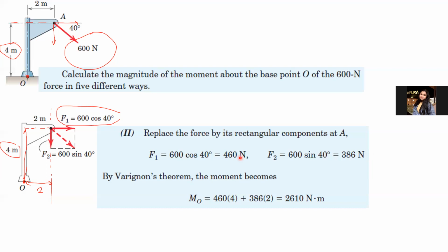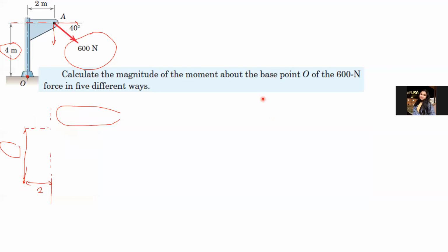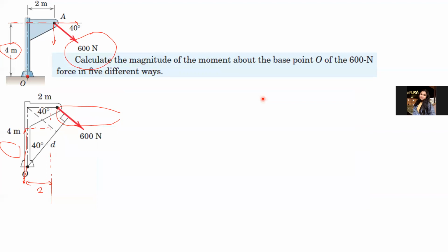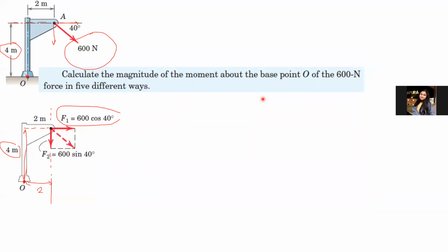Okay. This is how we can calculate the moment using Varignon's theorem. And remember, most of the time it will be easier for us to calculate the moment of a certain force using Varignon's theorem, because most of the time it is also easier to find the perpendicular distance of the force components instead of the force itself.